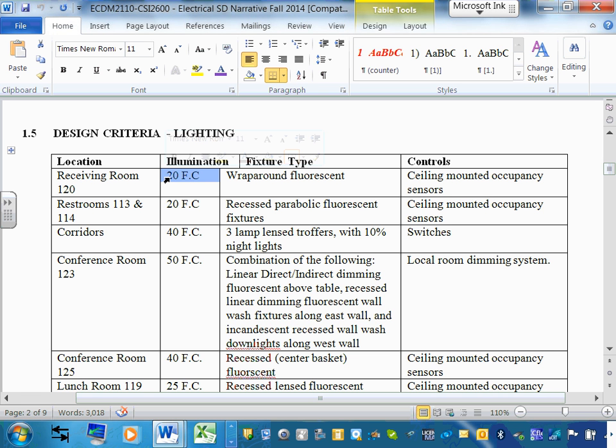To give you an idea, right underneath here, where you're sitting in this area, you're looking at close to 75 foot candle. If you go right in that corner where it's dark, you're probably looking at 20 foot candle. That gives you an idea what a foot candle is. We're going to do all these visual calculations to get you foot candle. We do have a class dedicated to lighting, so we'll go into details on how to do the foot candle, what it means, lumens, and what not.